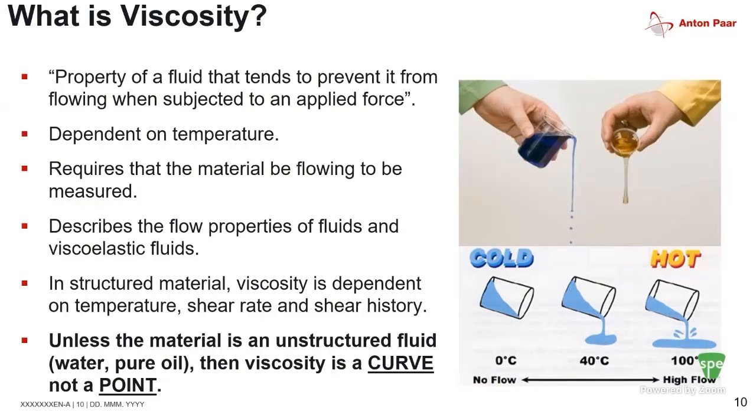In the case of materials, if there is no structure in them, we can talk about viscosity as a single point response. But in most cases, materials have some degree of structure. So you have to look at them as a function of a curve, because different shear rate conditions impact the behavior of the viscosity, and the viscosity changes as a function of both temperature and the shear history you apply to it.